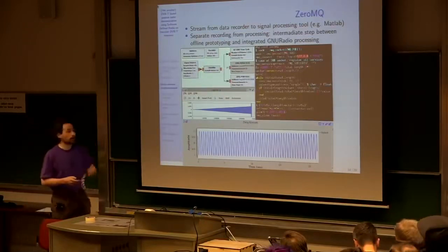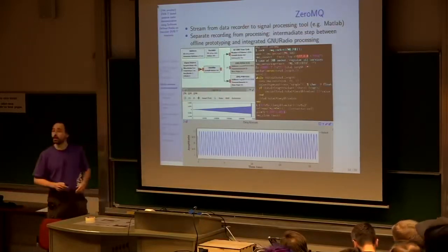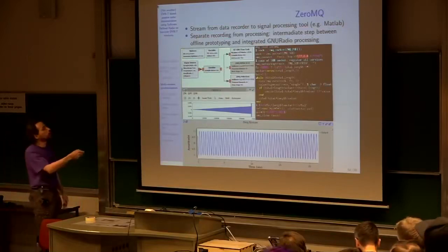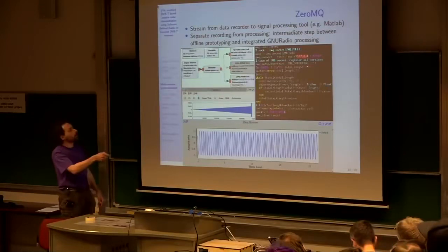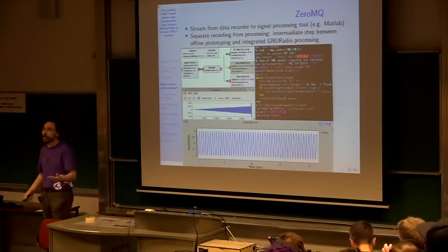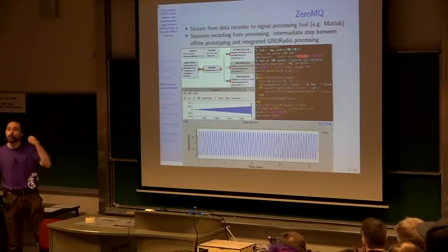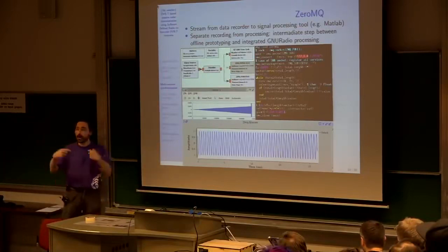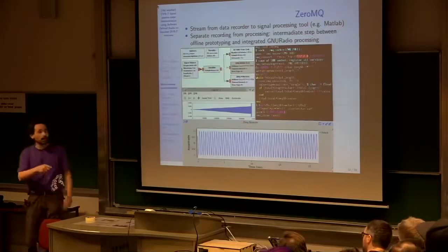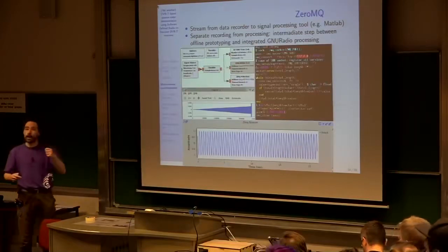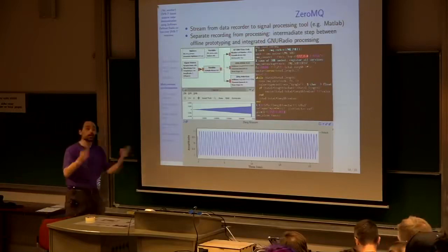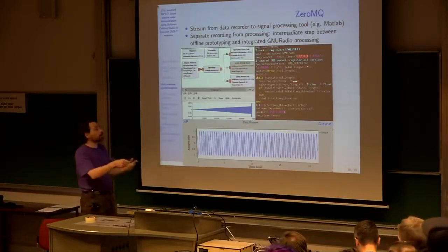Tom Rondeau explained to us that external software would be best used to collect data from GNU Radio. What we did here is we use GNU Radio to collect the data. We stream the data using a UDP-like approach, meaning that the data are continuously streamed. And because Octave has a 0MQ sink, we can collect the data just when we connect to the socket. And when we don't need the data, well, the data are just lost, but at least they are continuously acquired and they are just collected whenever we need them.